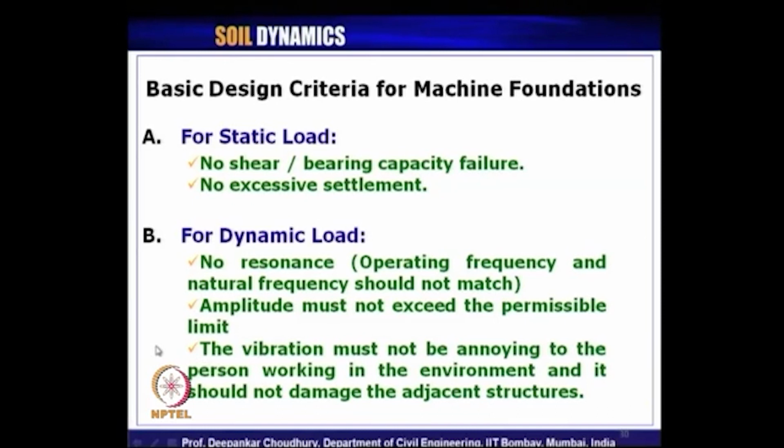So, when you are designing any machine foundation, you should not only provide a strong foundation which can take care of the dynamic load by assuring that it is safe against bearing capacity failure, excessive settlement under static load condition, as well as it is safe against the no resonance criteria, and this dynamic amplitude is less than the permissible limit.